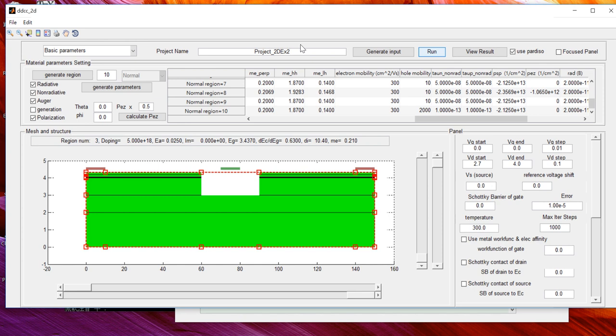You guys did that in the code, I think, with parallelization. It's not automatic. Does it support parallel computing basically? It supports multi-core, but not MPI. MPI is when you submit a job to different computers, the same job, and they run in parallel on different computers. It doesn't support this, but if your computer has multiple cores, it will use multi-core to accelerate the speed. So it'll do that automatically. Right now, for example, if you are running, you can check the CPU usage.